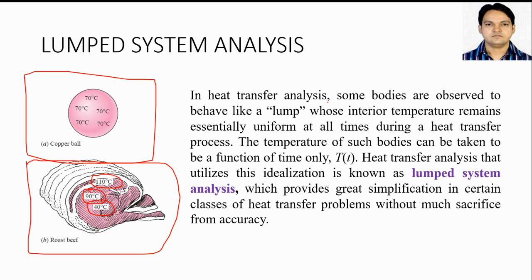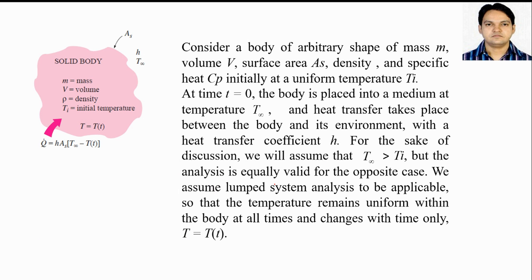In heat transfer analysis, some bodies are observed to behave like a lump whose interior temperature remains essentially uniform at all times during a heat transfer process. This is the condition. The temperature of such bodies can be taken to be a function of time only. Heat transfer analysis that utilizes this idealization is known as lump system analysis, which provides great simplification in certain classes of heat transfer problems without much sacrifice in accuracy.